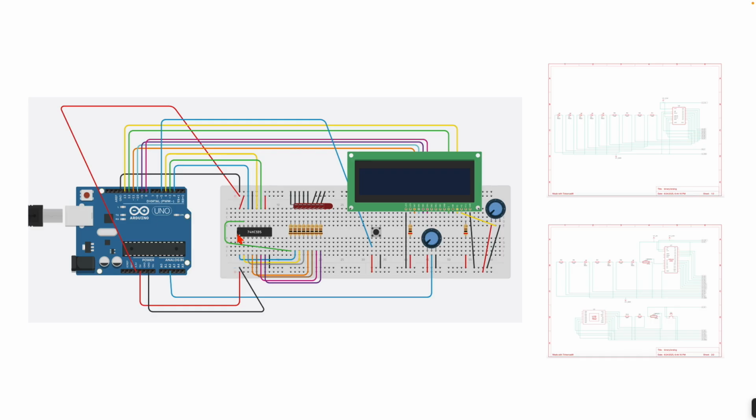So as I explained a bit earlier, it uses clock timing to control the outputs. You'll see that there's 3 lines here that come from outputs on the board. One of them is the clock timer, which will send a signal at alternatively high and low voltage, which will be used by the shift register to time and shift over the different outputs and send them in a line to the LEDs.